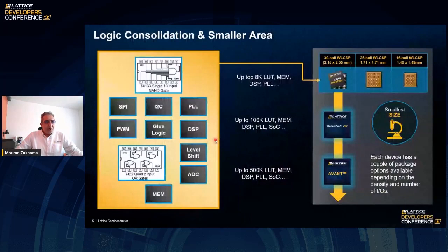As you know, FPGA stands for Field Programmable Gate Array. It is a sea of gates that could be used to implement any conventional logic, like seen in the slide. So you can integrate SPI, I2C, PLLs, PWMs, glue logic, some of the 74x type of logic. They could all be consolidated in one FPGA. And the smallest FPGA that we have in Lattice is called the iCE40 Ultra Plus.